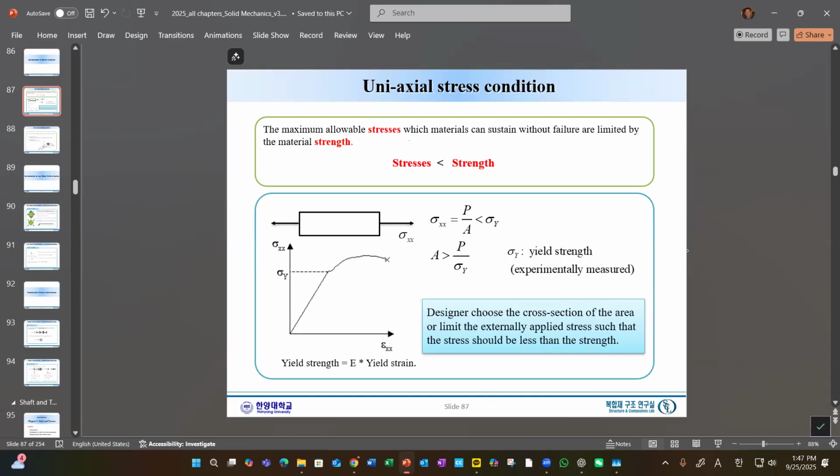So let's pay attention to a uniaxial stress case. We already know this is a material under stress, a very simple uniaxial stress. We have a sigma xx, and this is a strain. So stress, strain, this will deform like that. This is extension, right? And this much will be determined by the Young's modulus, the stiffness, which you already know. And this is a contraction which occurs under tension, and this is related to Poisson's ratio and Young's modulus.